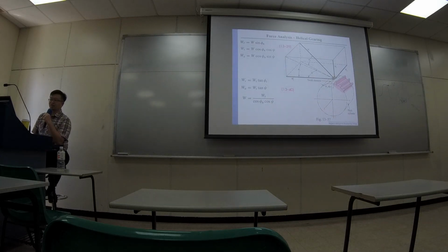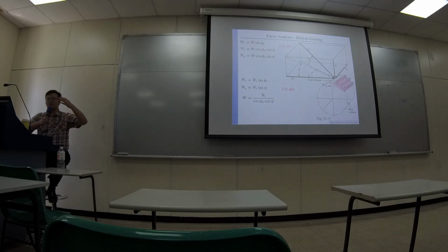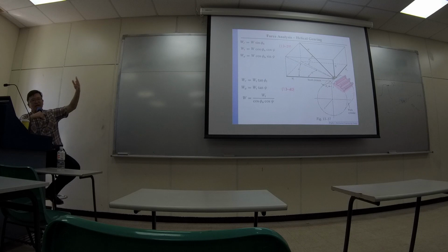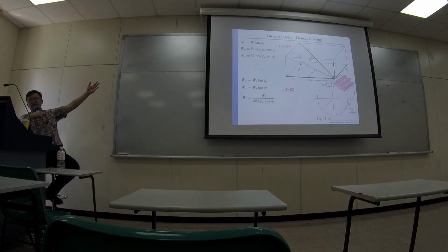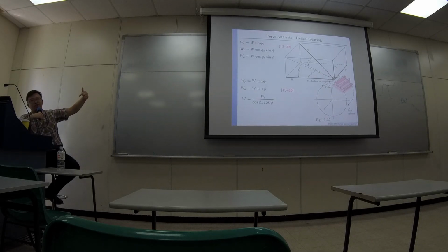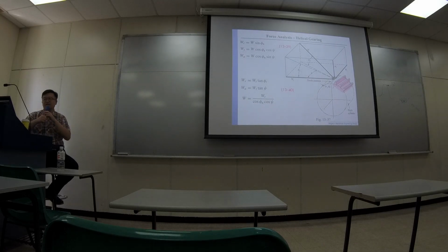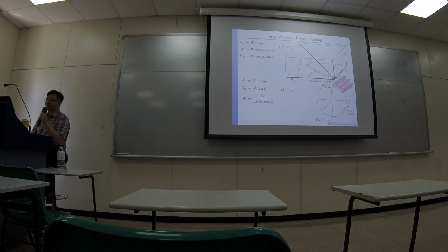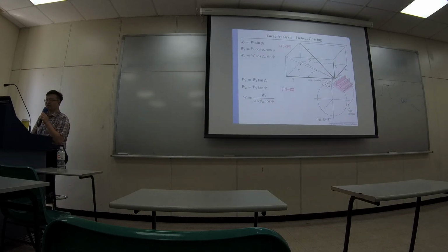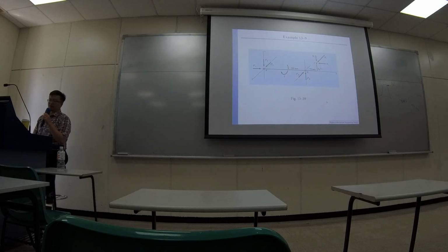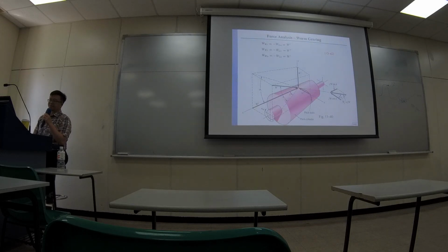This is about the helical gear. Similarly, because of the helical profile, the force coming from the opposite side of the helical gear follows a certain angle, and it's going to have 3 force components. Again, WT represents transverse, WR along the radial direction, WA along the axial direction. So it's quite similar, so I'm not going to cover those.